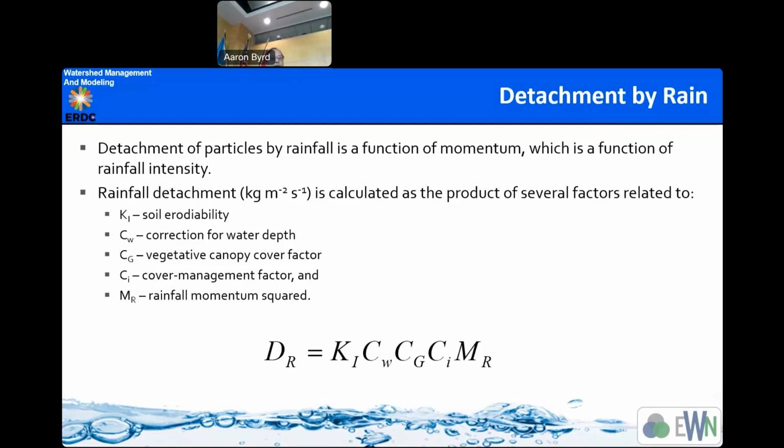More canopy resists the sediment from triggering from a location. And it depends upon crop types. If it is seasonal crops, that has more sediment detachment possibility. But if it is evergreen grass, that has more capacity to hold the sediment back. So all these factors are empirically derived, but are well used in several equations or well-known modeling platforms like WEPP and GSHA and all those models.